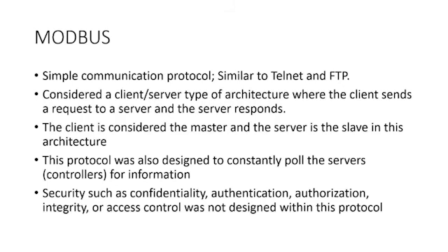So Modbus is considered a client-server type of architecture where the client sends a request to the server and the server is going to respond. So the server could be like those PLC controllers, where the client is us. We send that information off. Now, the client is considered the master, which would be you or me as the controller sitting at the management station, and the server is the slave.